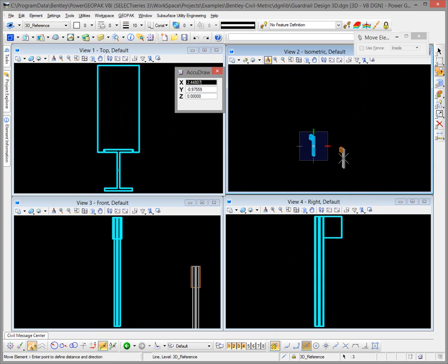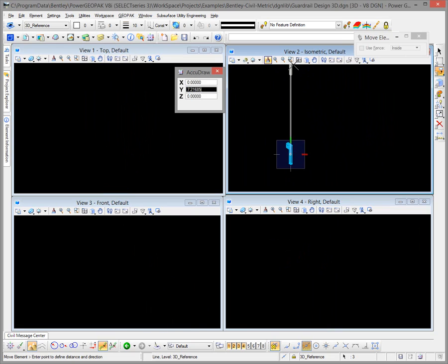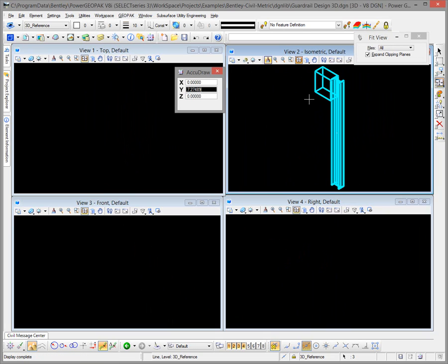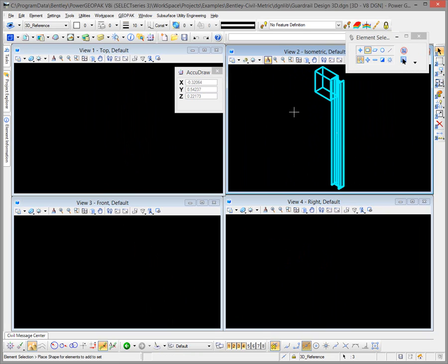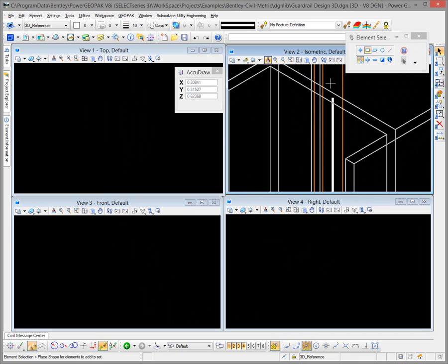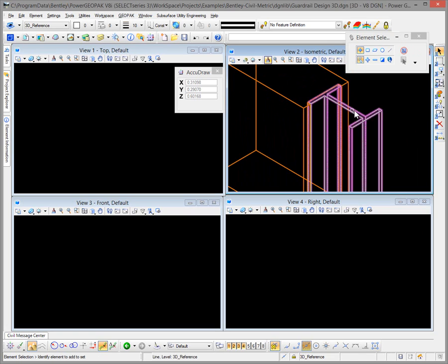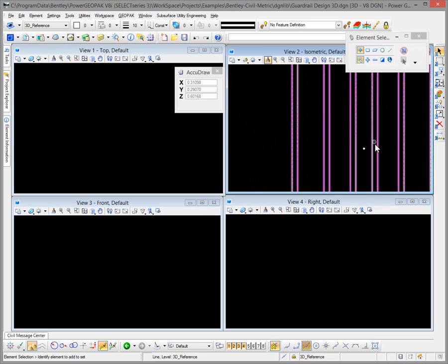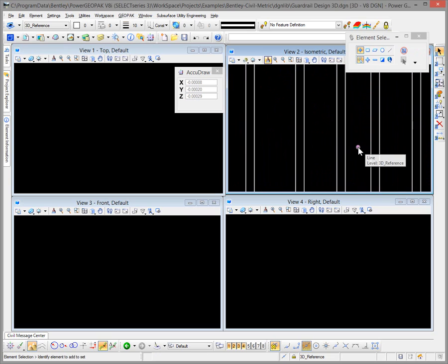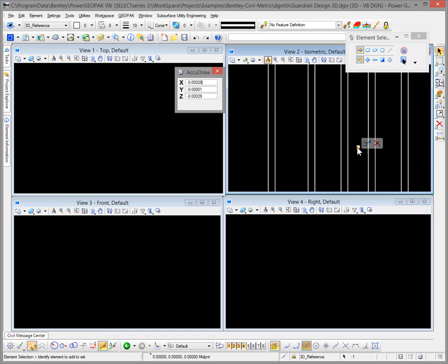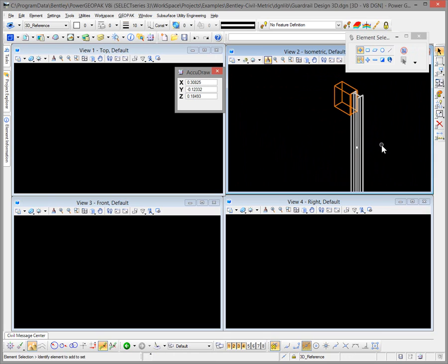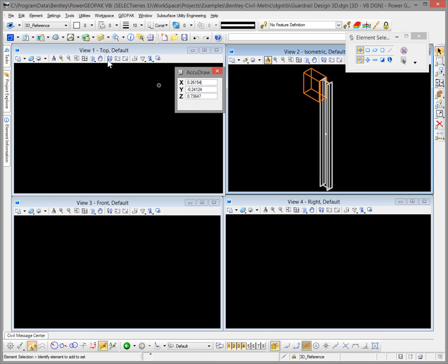And then I'm going to zoom out here, window out, and we're going to move it to our new point down there. And then when we do a new fit view, we can cancel out of our move command. Now we can come in and actually delete our construction line. We're done with that. And so now we're going to have this point down here that we can use as our cell origin if we want to make a cell, and that coordinate is 0, 0, 0, and then we have our guardrail set at the proper orientation for that cell.